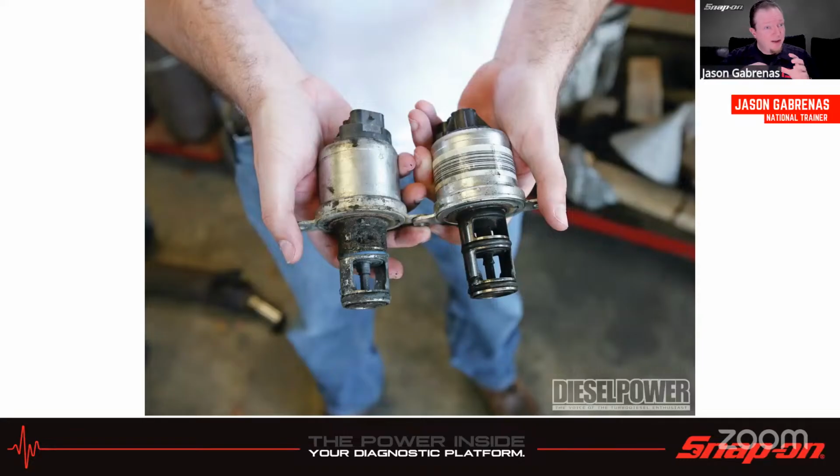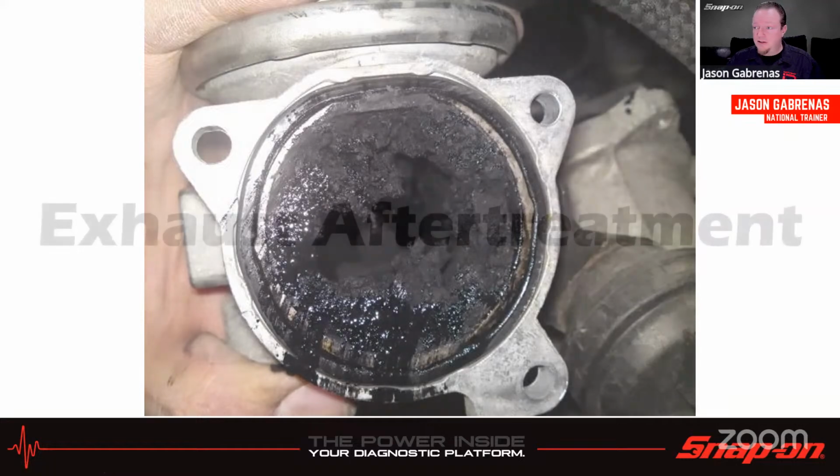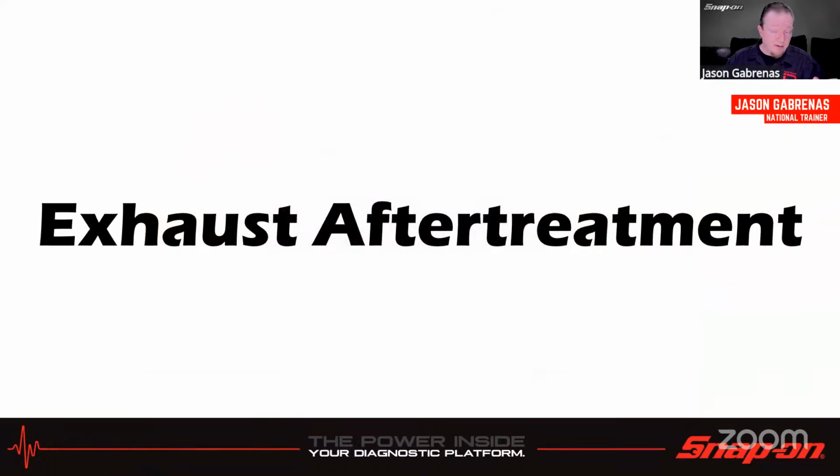So now since we've changed the combustion temperature, we have more soot and we can clog up inside that EGR valve right there. You can see all that soot in there. So those have to be cleaned. Soot plugs the valve, the EGR cooler, etc. I've talked to plenty of Snap-on guys on their Snap-on trucks like, oh yeah, my EGR cooler is clogged or whatever. So that is a possibility. The EGR or EGR cooler can do that, can clog. So that's one thing we've got to worry about. Just take it out and clean it off. Should be okay, I would say.